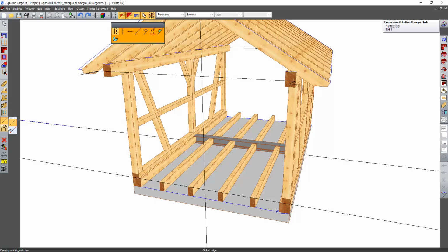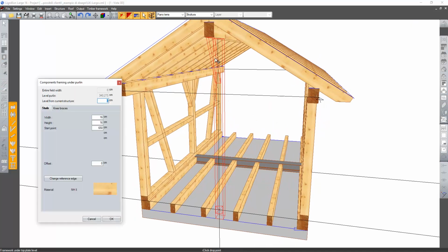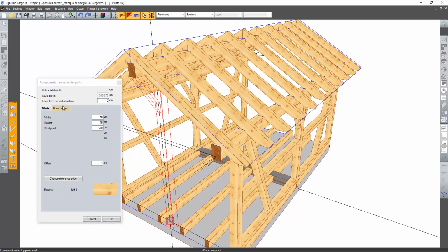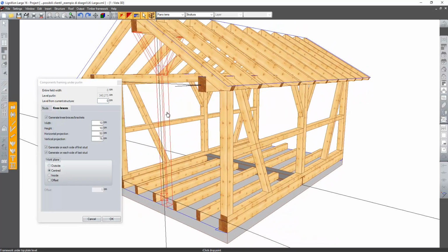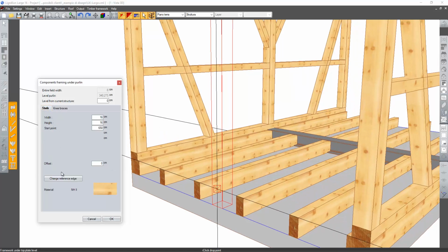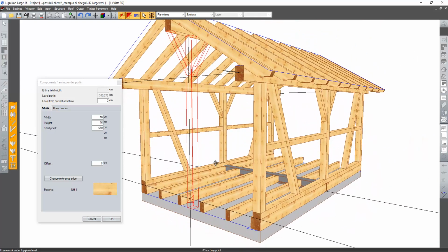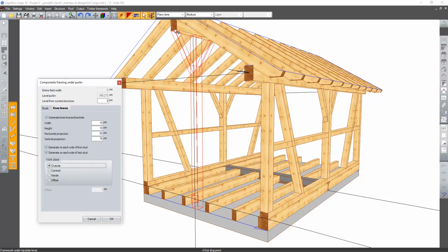Okay, now we go again here in our element. So we click the point, click this beam, click this point, and you can see we are putting it exactly there. The knee brace we put in the second, and we confirm. And we are drawing exactly where we put the guidelines. Here you can see changing the reference, but we are right with this reference, so we confirm it. Here also the knee brace, you can see this is the reference that we were watching now. You can say centered or with an offset, and you decide how much.